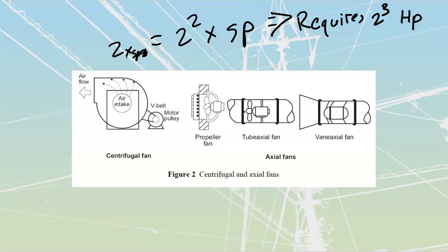Once again, if you're working with one of these systems and it's undersized, they're going to have to change the motor. If they change the motor, you're usually looking at a significant size change to the actual conductors that you're going to place inside there. Oversize your conduits for these things. I've dealt with it in the past where stuff has had to get changed. The engineers are not always correct.